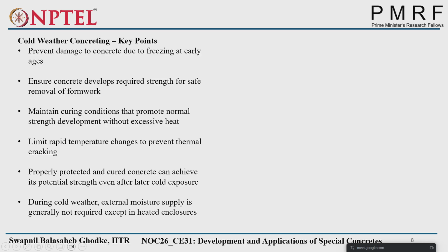So properly protected and cured concrete can achieve its potential strength even after later cold exposure. What it indicates, that same graph also means if we initially protect the concrete and cure it properly, its later age frozen condition will not affect its strength. We saw for 36 hours, right? For 36 hours, there will not be any impact of frozen conditions.